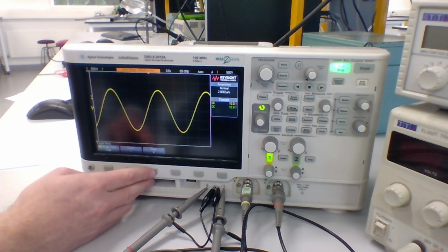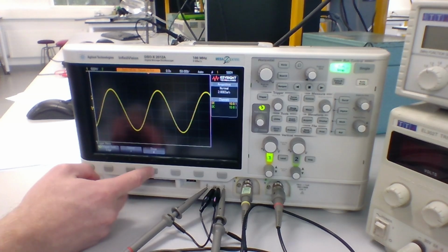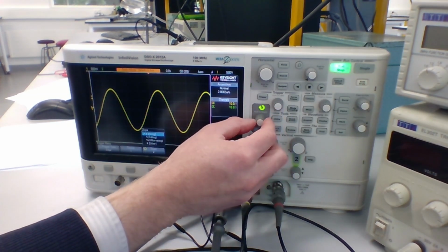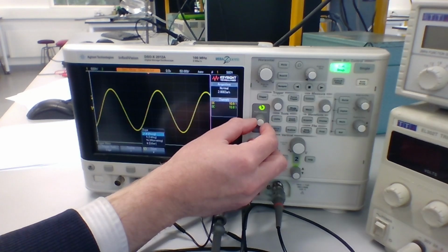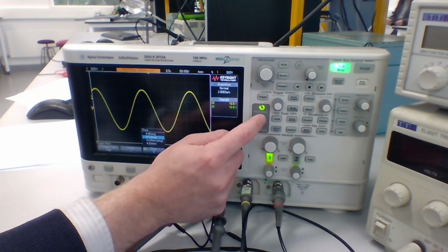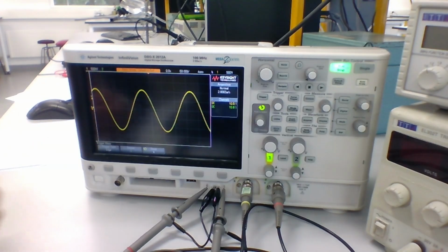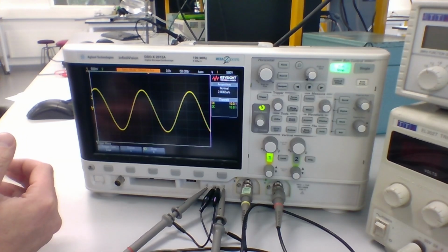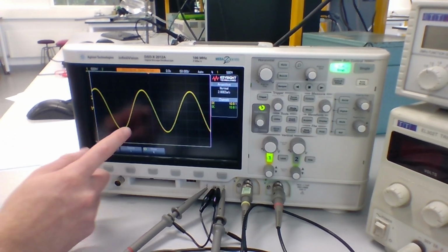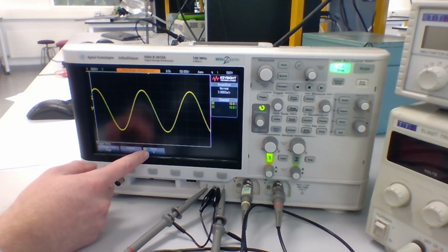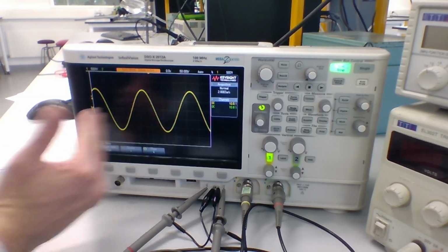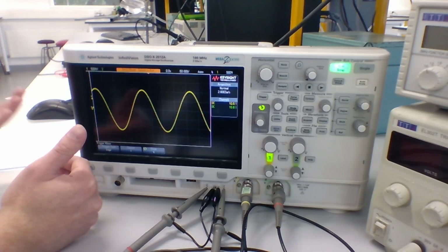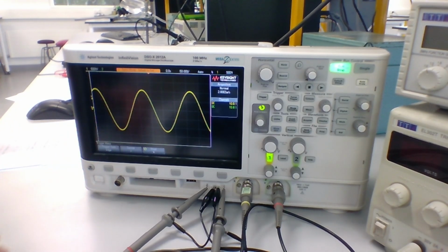If we want to, we can change that. So following the instructions, we can press this button and rotate this dial to change that to be a falling edge. If I press that to select it, we're now measuring on falling edges rather than rising edges. This can be useful for different types of waveforms. You can see now that by changing from a rising edge to a falling edge, the waveform has moved on the screen. We've effectively inverted it because we're looking at this waveform when it drops down, the voltage decreases, rather than when it increases over our trigger threshold.